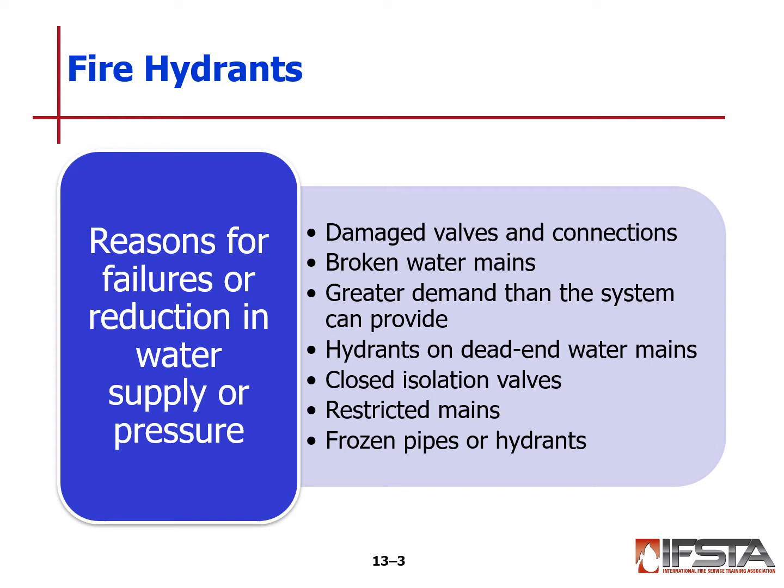And what that means is in a grid system where typically you'll have a fire hydrant placed about every 500 feet, in the very dead end of a subdivision, as an example, where it is not looped, and that's the very end with no loop back, then that fire hydrant could potentially produce less gallons per minute. And remember, from fire dynamics or fire behavior, we've talked about how we think in terms of gallons per minute. We want to see those green and blue fire hydrant colors so we know that they're going to put up to 1,000 gallons per minute or more.